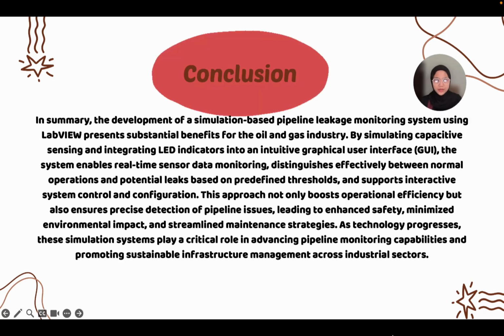As a conclusion, the development of a simulation-based pipeline leakage monitoring system using LabVIEW presents substantial benefits for the oil and gas industry. By simulating capacitive sensing and integrating LED indicators into an intuitive graphical user interface, which is a GUI, the system enables real-time sensor data monitoring, distinguishes effectively between normal operations and potential leaks based on predefined thresholds, and supports interactive system control and configuration.